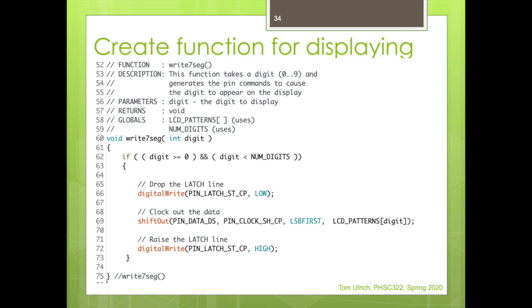I say I'm doing it LSB first, that array I did is LSB first. And then what I do here is I have a reference to the array and I index the array with the digit. And that'll send the right pattern. And then I raise the latch line.